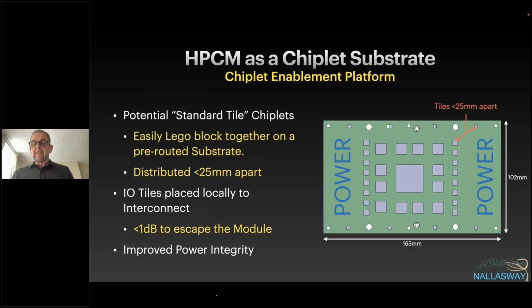Yeah. So there is one technical issue that is more based on the current state of the art. That is, the organic packages typically today are yielding in the range of, say, 80 by 80 millimeters. That's why you see those sockets. They are in that range. Yielding organic at 102 by 165, haven't seen anything. We've definitely seen packages in 100 by 100, but that doesn't mean that there wouldn't be a technology. I'm sure there will be some technology that can support it.